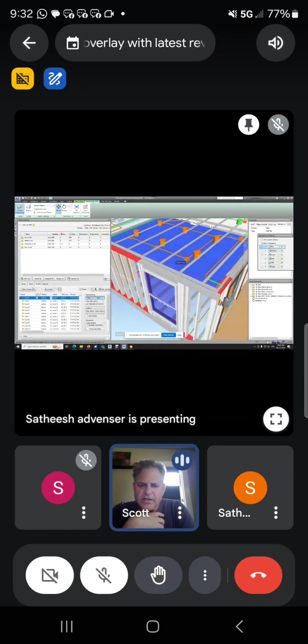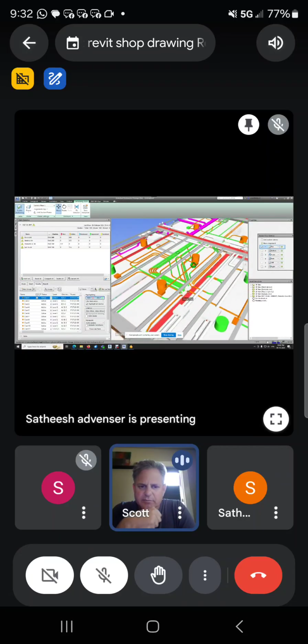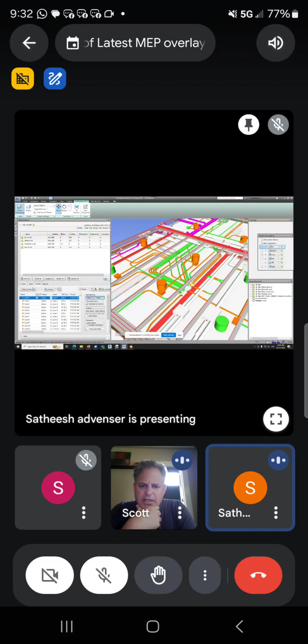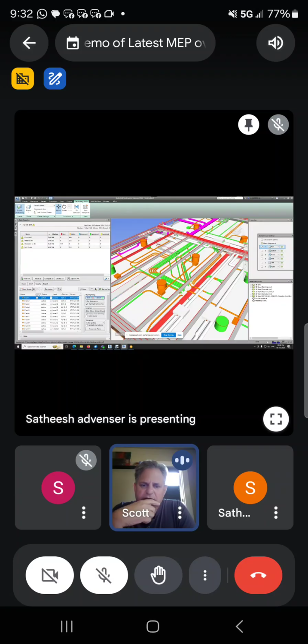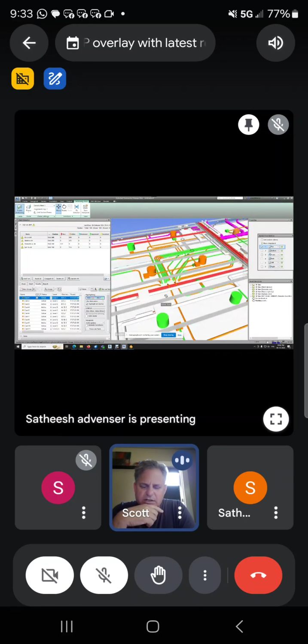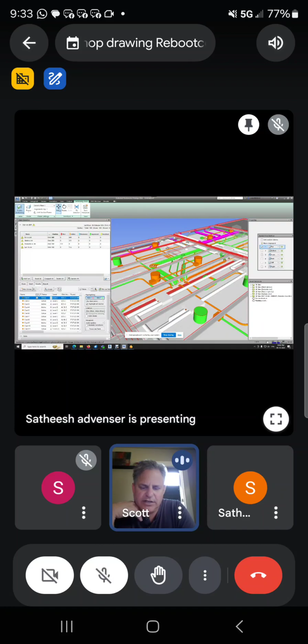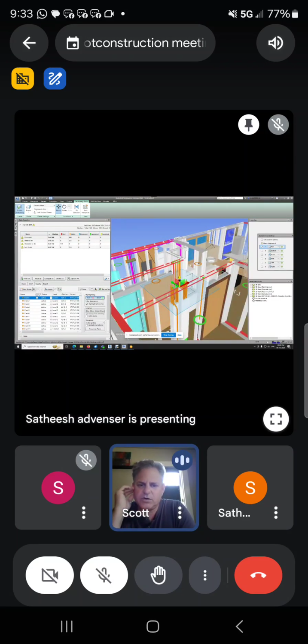Is it going to be like what we call a Smurf pipe, like a plastic pipe that kind of moves around? Yep. PVC. So we need to know how we are going to get those corners to bend, because the wall's going to come. Is there going to be a piece of flex that goes in between conduit to conduit? These are things that we need to work out, but you're helping us work these out.